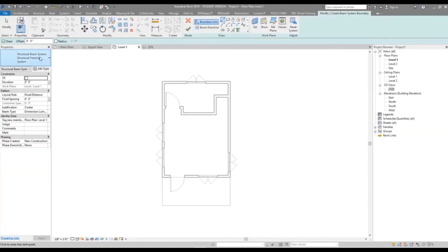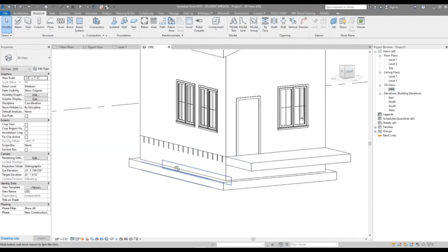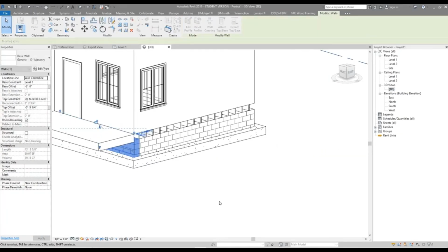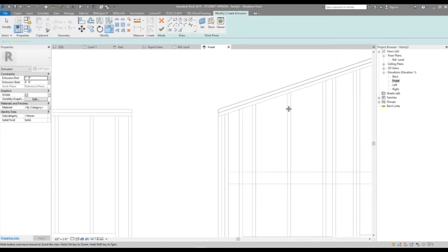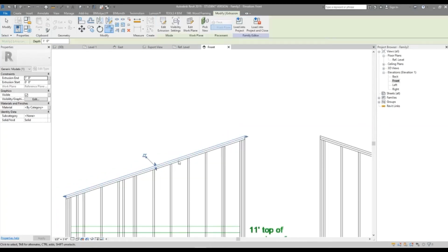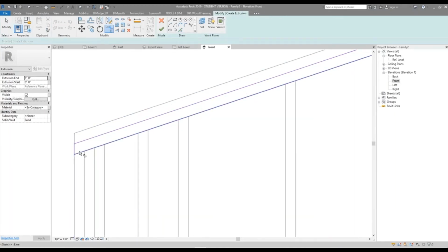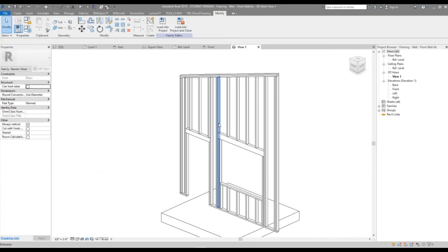From there, it was time to start increasing the level of detail of the model. So I then modeled in as much as possible with the built-in Revit tools. To give an example, the floor joists and roof rafters can be modeled using the tools in the software. To continue adding more detail, the family modeler in Revit had to be used. Families in Revit are objects that are grouped together as one model. This is where things such as the wall framing, corner boards, and more or less everything that needed to be explodable was modeled, with the exception of the curved parts as I previously covered.